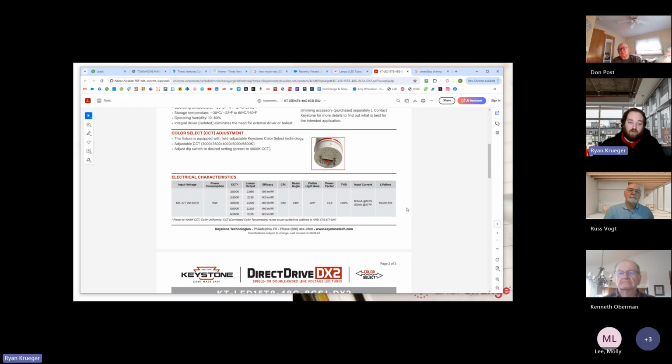The higher you go in lumens per watt, the brighter the fixture is and the lower the wattage is. Right now, I think TCP was able to hit 210 lumens per watt, so you can get a lower wattage fixture with the same light output and drop 10 to 15 watts, depending on the application.